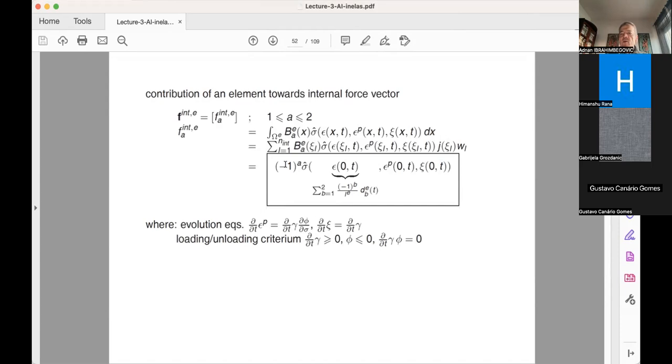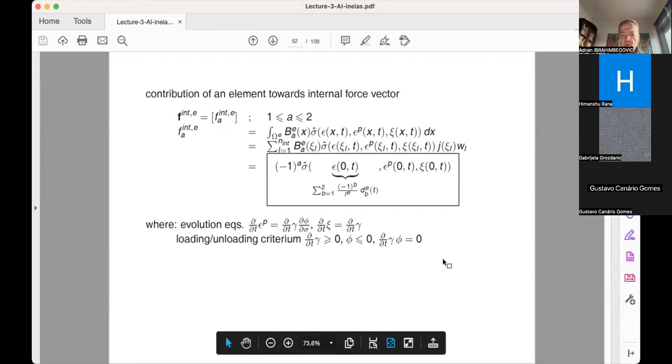Also, the other point is the plasticity in one element is completely unrelated to a plasticity of another element. Relation of these two things will come only through the global equilibrium equation, when finally the element which is yielding, that's actually becoming less stiff, is through the equilibrium equation saying to the other guys, I can no longer take this load, so I have to unload. So here somebody should be able to take it instead of me. And that's really the idea that actually follows into this type of computation.